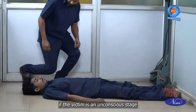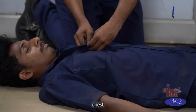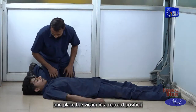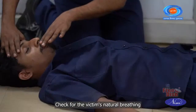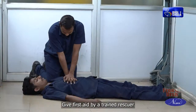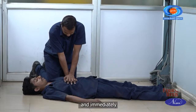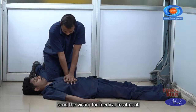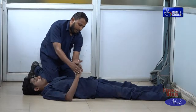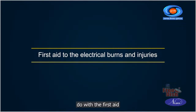If the victim is in an unconscious stage, then loosen the clothing of neck, chest and waist and place the victim in a relaxed position. Check for the victim's natural breathing and consciousness. Give first aid by a trained rescuer based on the condition and immediately send the victim for medical treatment. Keep the patient warm. In case of electric burns or injury, do the first aid.